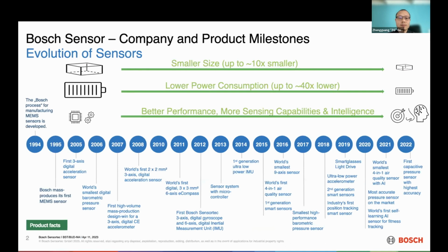So here it's worth mentioning that when we are talking about power consumption, we need to look at the bigger picture. Of course, saving a few hundreds of microamps of current on the sensor alone does not help much if the power-hungry processor must keep awake to process the sensor data. Over the years, a lot of sensor features and new system architecture have been introduced, such as a deeper FIFO memory on the sensor, and more importantly, localized sensor processing, which have been able to reduce not only the power on the sensor, but also the system power.